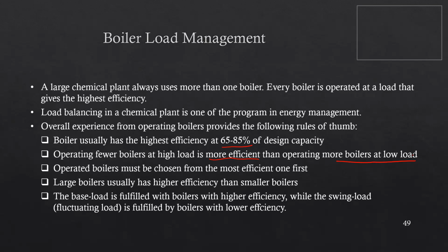Okay, the third rule of thumb is that operated boilers must be chosen from the most efficient one first. We can actually calculate the boiler efficiency, and we choose the highest efficiency in the first operations of using multiple boilers.